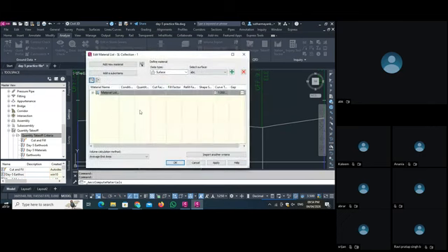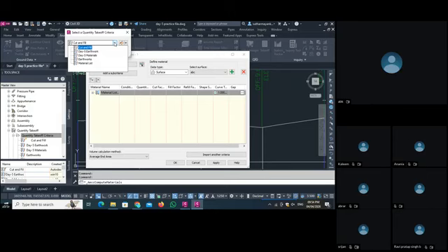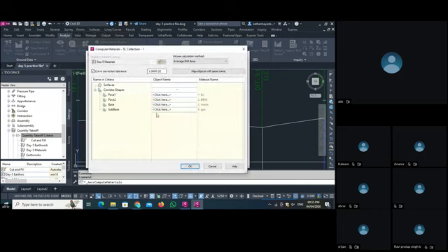Now you see this type of pop-up box. The same. If you see this, what do you do? You click here, import another criteria. This one criteria is the set material list. I want to import the second criteria, so import another criteria. And what do I have to import? Day 5 material that we created. I say OK. As I say OK, now we see here day 5 material is there. Whatever we created, day 5 material, it is here.